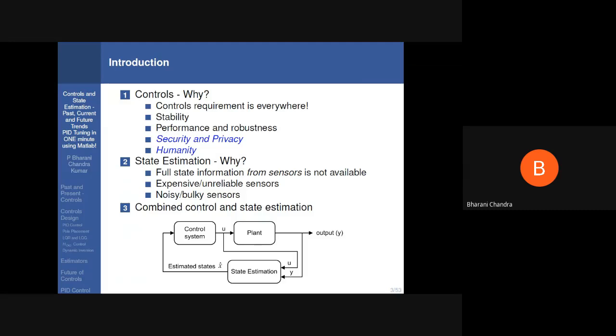So for this purpose, why does one have to go for the state estimation algorithm? If I want to go for sensorless control, and here sensorless means mechanical sensorless control, that means I don't want to use mechanical sensors for the state estimation. Rather, is it possible to use the current measurement, calculate or estimate the speed from it, and give the estimated speed to the error comparator, and whatever error is generated, the control can be built from that.